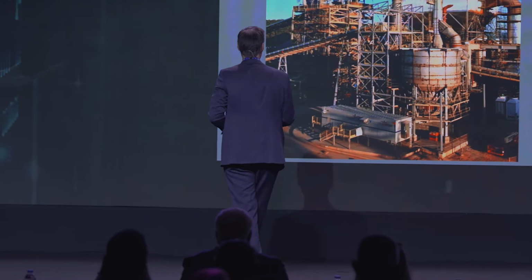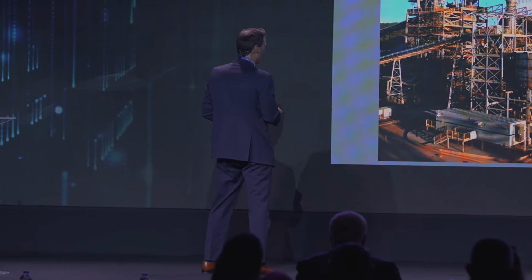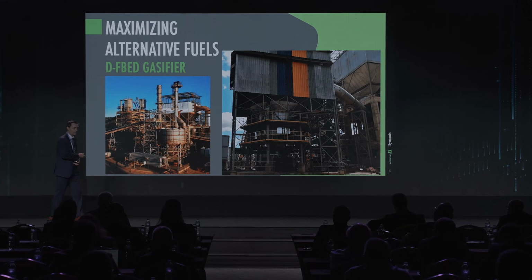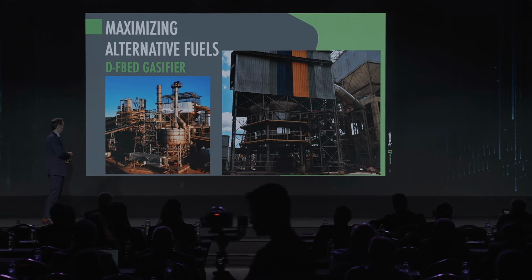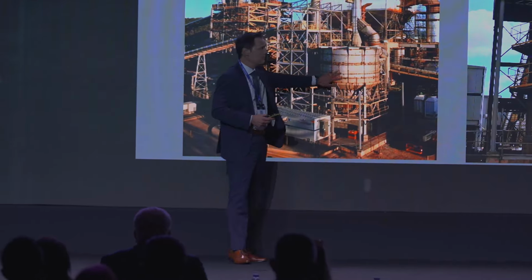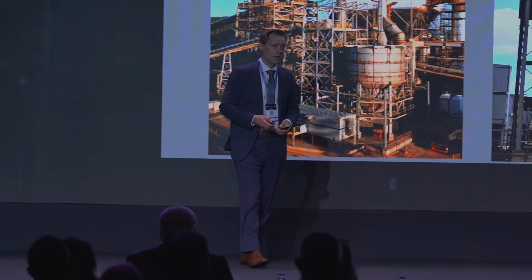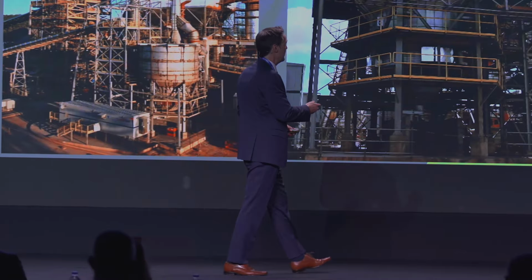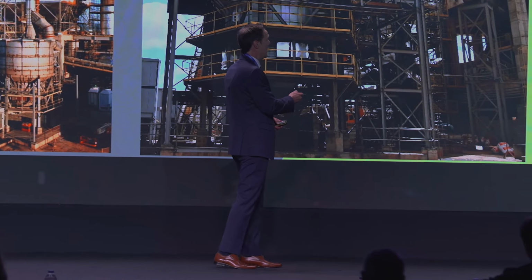The solid fuel here is conveyed from the storage to the dosing system by this belt conveyor and introduced to the gasifier by a dosing system located in this building here, right? So internally, the gasification process takes place in this equipment, and the generated syngas is connected to the process by a duct.